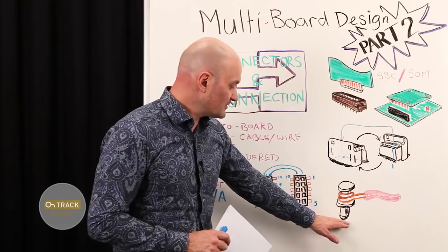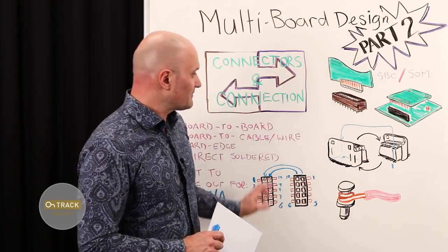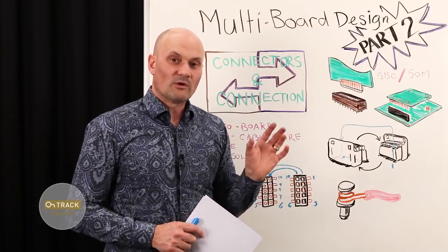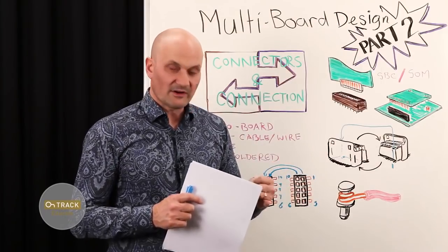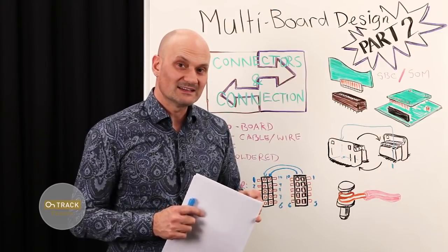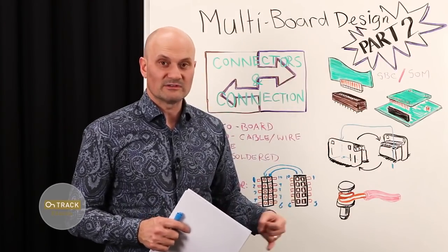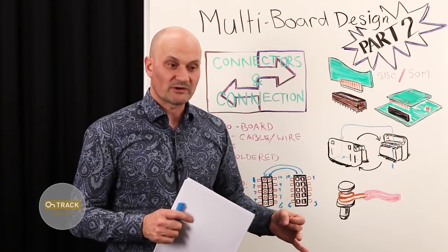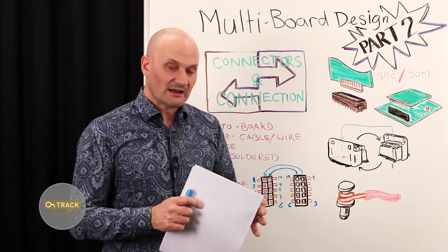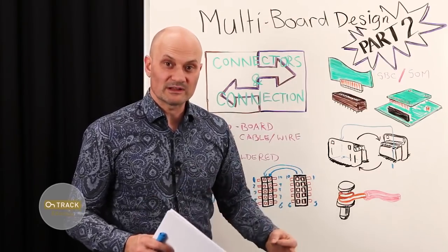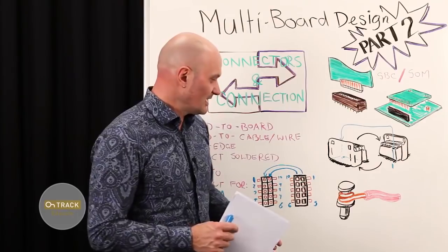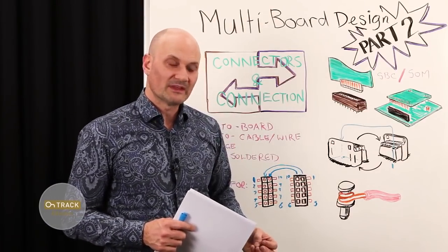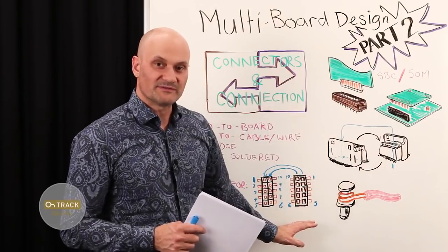there is an industry standard for these and for all other kinds of connectivity to specify what the quality should be. If your design is IPC Class 1, that is low-cost, mass-produced electronics, it doesn't have to be reliable, or Class 2, moderate complexity designs, or Class 3, sort of high reliability products like military, aerospace, each have different requirements for soldering quality for all these different kinds of interfaces.